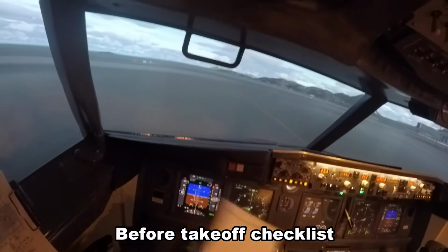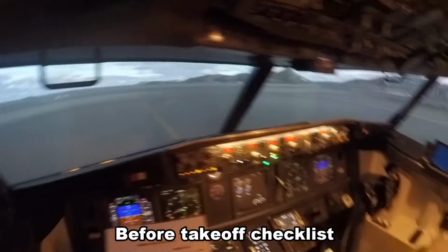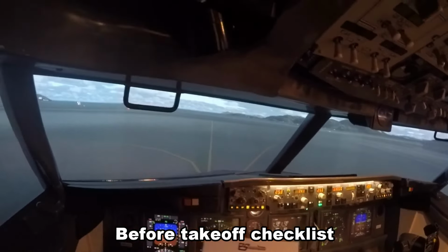So we'll do before takeoff checklist. So flaps are 5, green light, stabilizer trim is 5.3 units. Before takeoff checklist is complete.